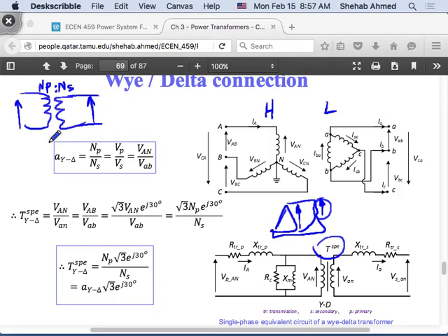This is before we go to per unit. Remember, before, we read the problem and draw the impedance diagram or the single phase equivalent circuit with real values, right? In here we will still have the transformer with its real turns ratio, but now the real turns ratio is not a pure number for a star delta transformer, right?